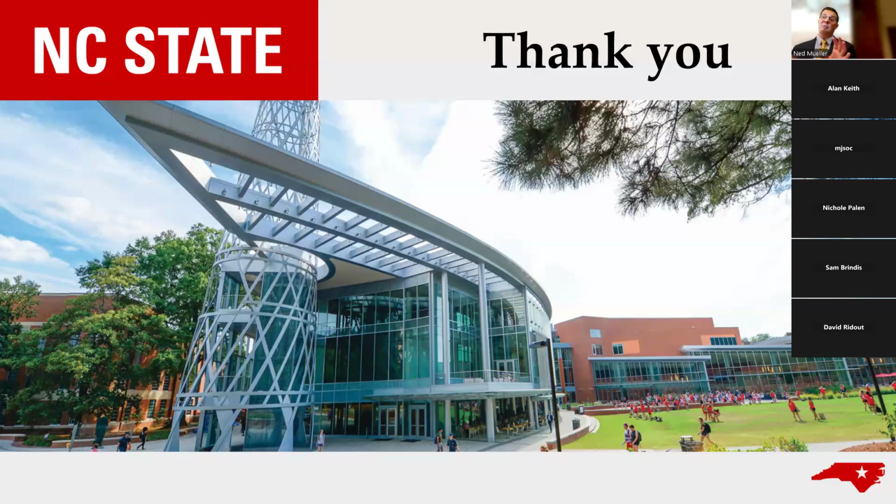I think what could be possible in the future is even something finer than 0.25. That's sort of a baked in, implicit number, but it's not the critical number in a location that has a high cross slope and a large longitudinal slope. It's 6 lanes wide. Tools like that are going to allow us to look at this in a more discrete way and identify critical rutting at a given location.